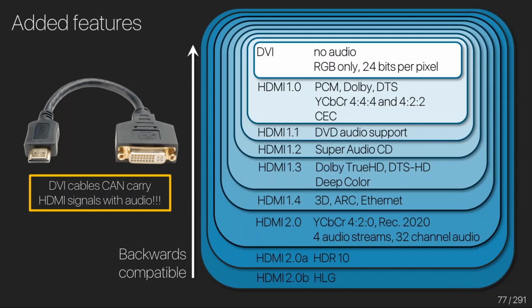So it's worth making a distinction here between the HDMI and DVI connectors and the HDMI and DVI signals. So you can send an HDMI signal over a DVI connector because they're backwards compatible and they share a lot of the same things with the 4 TMDS lanes, the DDC channel, the plus 5 volt, and the hot plugs. The connectors themselves are actually very similar, whereas the signal types have some key differences.